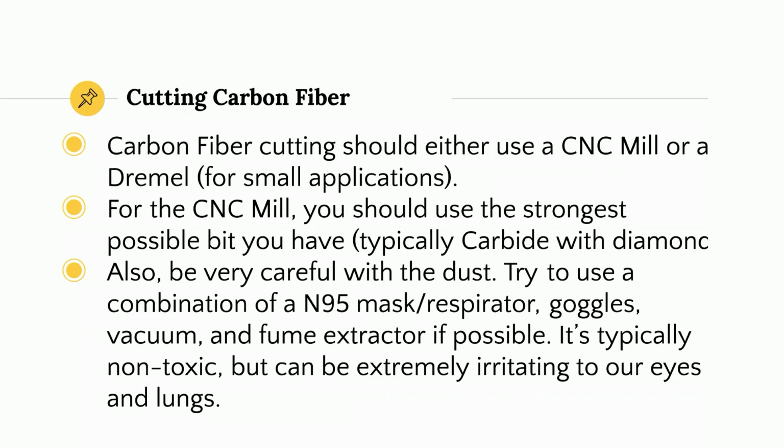You also want to be very careful with the dust. Try to use a combination of an N95 mask or respirator. No typical cloth mask for COVID. No, we're going to use an N95 or a respirator. Goggles, a vacuum, and a fume extractor if possible. You really don't want the stuff to get into your eyes. It's not toxic, but it is irritating, and you just don't want it. Better to be overkill.